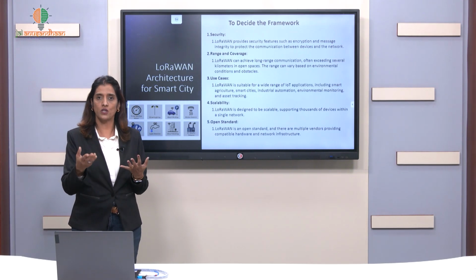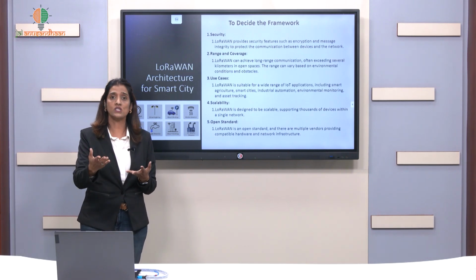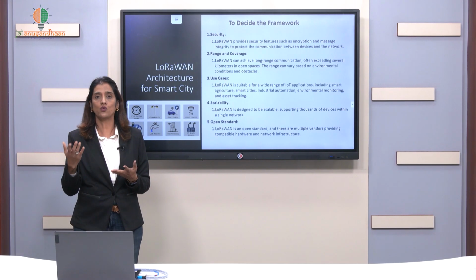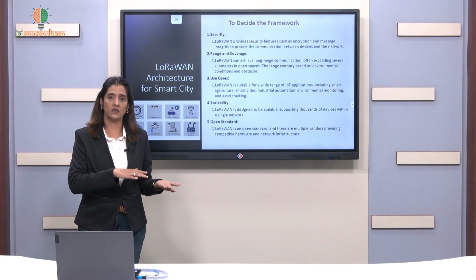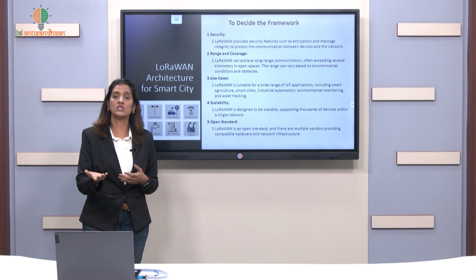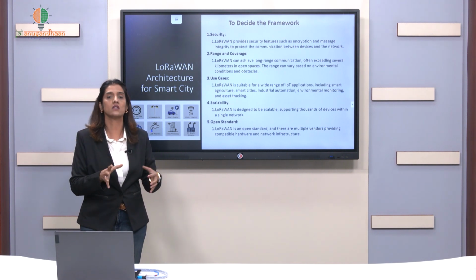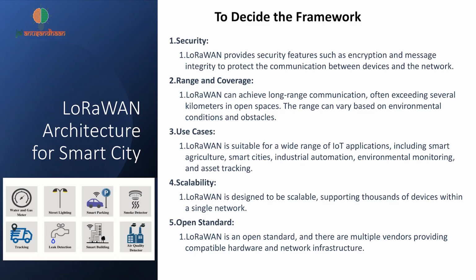What type of communication protocol is available in that plant, whether those gateways are available in the market, whether you are able to convert one type of data to another type of data, what type of cloud service is available. All these parameters decide the use case on which you want to work. The next is scalability: how can we scale up this application, what are we looking for from this application in the future.